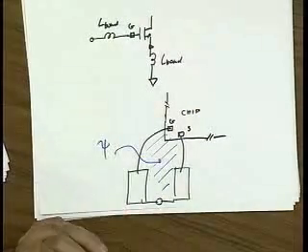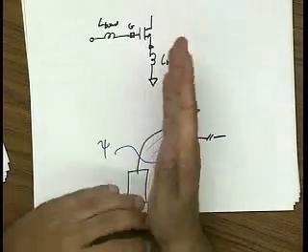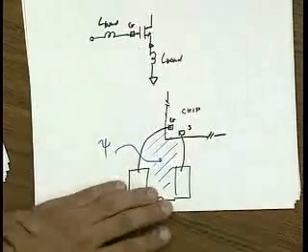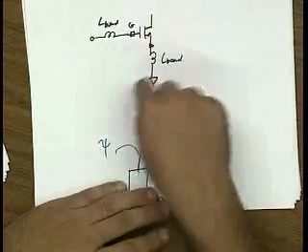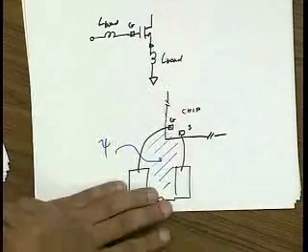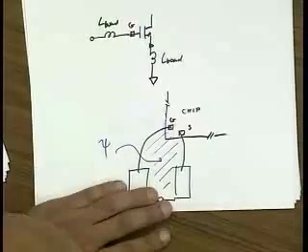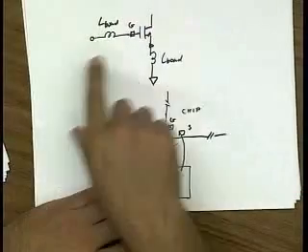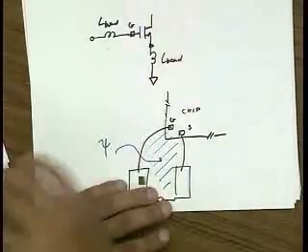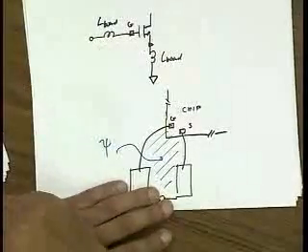Now, at first it looks like these bond wire inductances are going to hurt us. Next lecture we'll see that actually these things are beneficial. We can use them to become part of our matching network. And there's a few benefits. One, these are very high Q inductors. So unlike the inductors we put on chip, which have low quality factors, these things can have quality factors of around 30 at a gigahertz. Whereas on chip, we're looking at quality factors of 5 or 10.